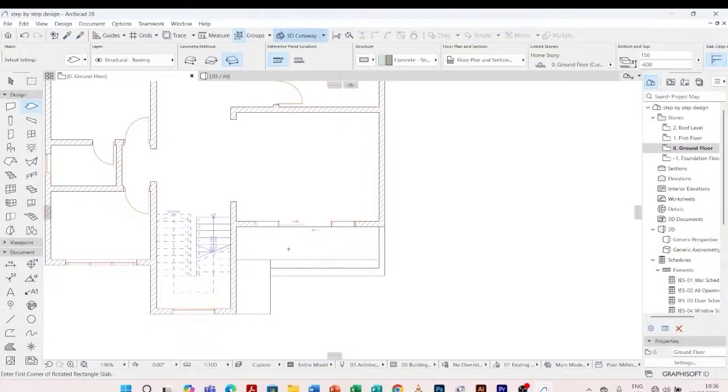The magic tool is the space key on our keyboard, whereby when I've clicked on the slab tool and I've done all my settings, I don't need to draw here. That's why we did the lines before. So after clicking on the slab tool, you hold on to your space key, you click on this space.